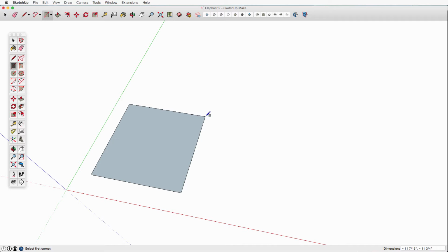And why you do this is if you were going to be inserting dimensions. So if I wanted to draw a 12-inch by 12-inch square, I can click, move my mouse just somewhere, type 12, 12 and hit enter, and I've just drawn a 12-inch by 12-inch square. If I were clicking and dragging, that's hard to do. But if I click, move my mouse, release, put the hands in the air, type 12, 12, and I've created a 12 by 12 box. All right, so I just did an undo with a Command Z or an Alt Z.